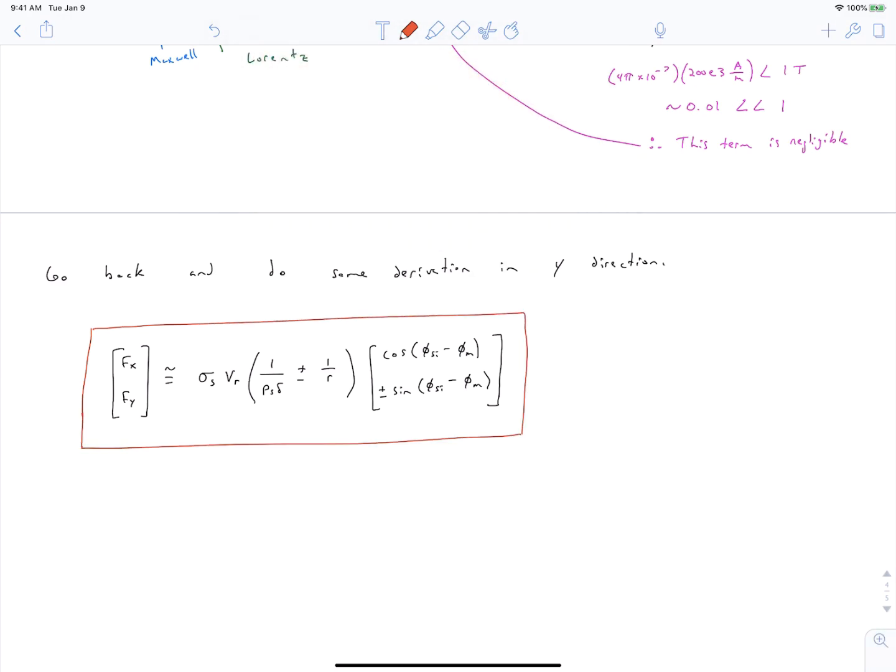And so along the way, we came up with expressions for all these subcomponents in here. The main thing to note is the sigma s, we said was bm hat times as hat over 2, where bm hat is the result of our magnetizing field added to our torque winding field, or the armature reaction field.